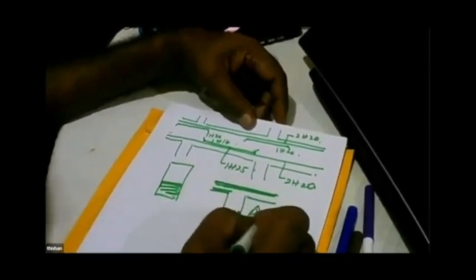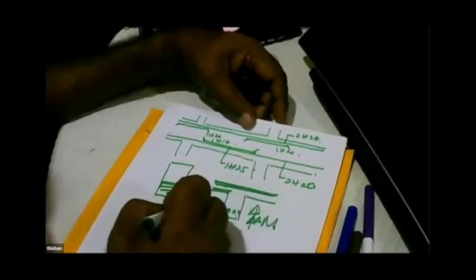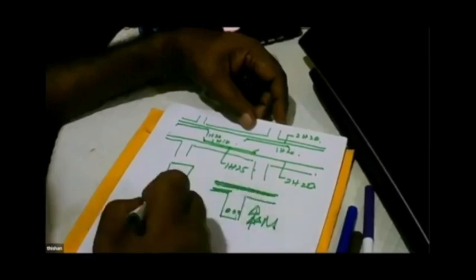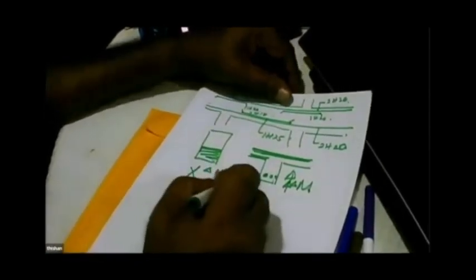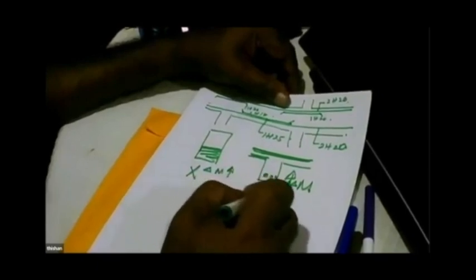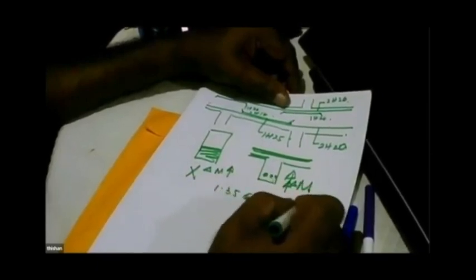This will have a huge increase in moment capacity. Delta M is very big. Here the delta M is very small. So no point in providing anything. So provide less. Even if you provide less, the amount that you lose is very small, whereas by providing more here, you are going to gain a lot. Anyway, you have to keep in mind that we have 1.35 Gk plus 1.5 Qk.